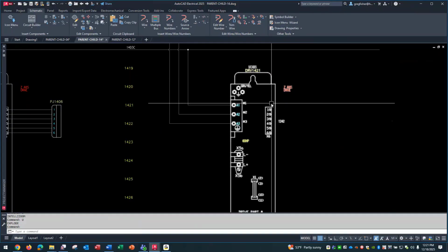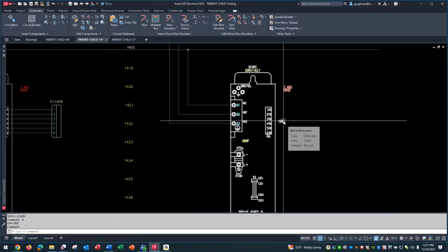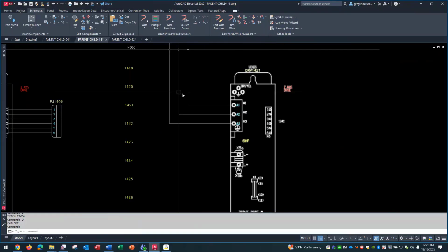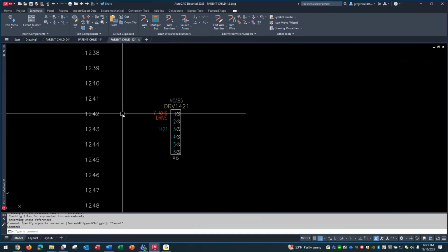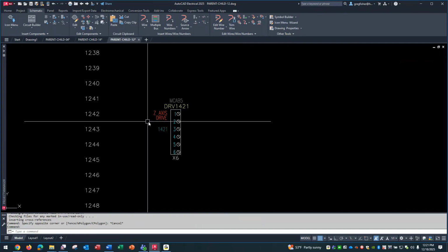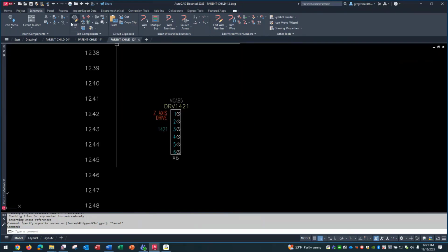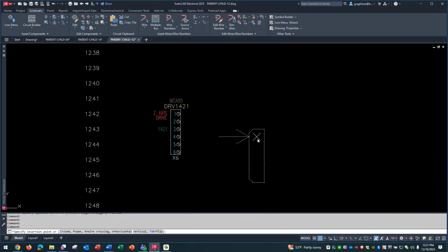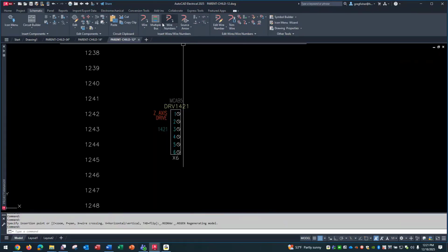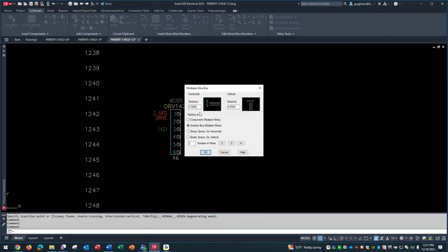And then the child symbol portion is cross-referencing to reference number 1242, which is right here. So all that works the same. And again, if I wanted to drop down another symbol in a separate drawing, now let me throw my wires down first. That'll make it easier.